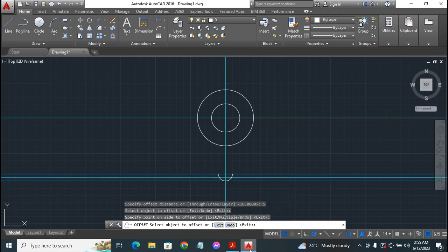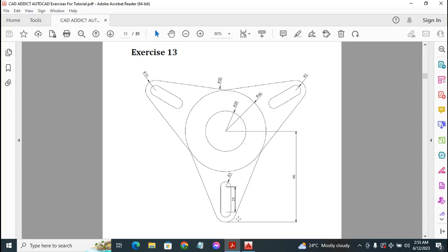So next up, from our PDF document, yes, the radius of this curve is 5 millimeters. That makes the entire circle 10 millimeters in diameter. Right from the center here down to this other center here, we'll have a 25 millimeter distance.